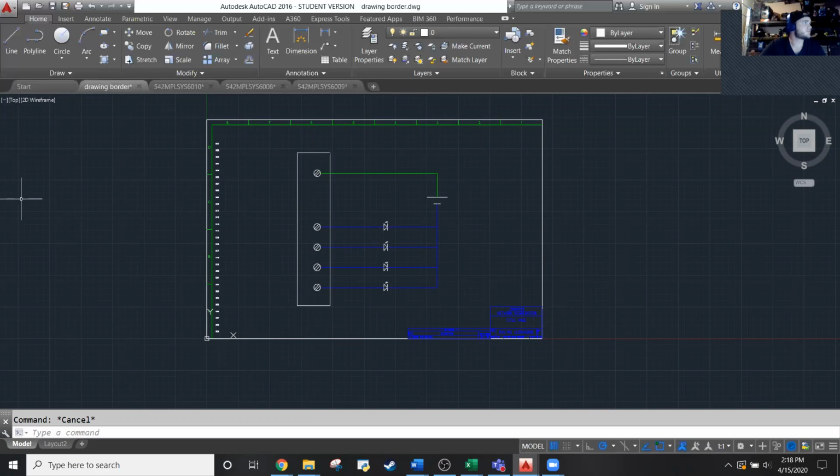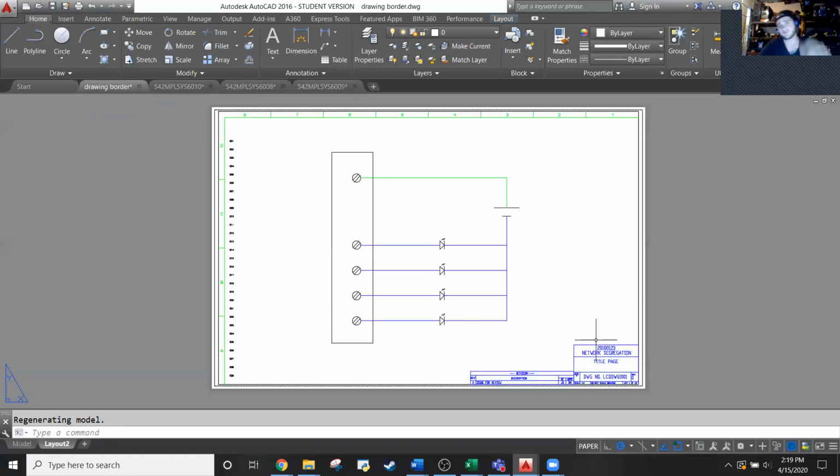Okay. So we have a comment here that some layers didn't show up, and then they deleted the layout tab and opened a new one. It fixed itself. This is one of the isms of AutoCAD that even if I worked through it and fixed it, I might not be able to tell you what is going on here. There's all kinds of controls with turning layers on and off and hiding them. That would be my guess as to what is causing the problem of them not being visible in the layout tab, but without poking through it, I can't tell you for sure. But that is definitely one fix, is to just open a new layout tab.